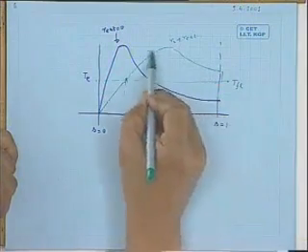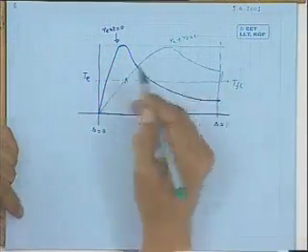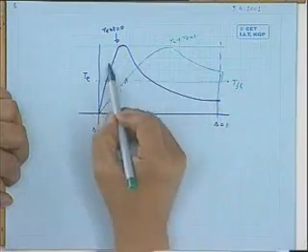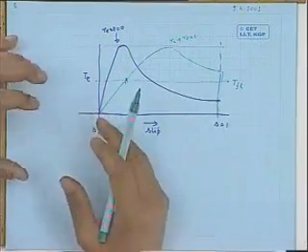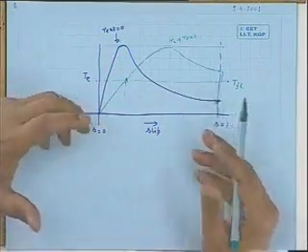So, as the machine now picks up speed, then like your DC motor, what do you do? You cut out that resistance. As the machine picks up speed, you cut out that resistance. This Tmax level is the same here. You go on, cut out that resistance gradually and bring it to 0. So, what have you exploited? You have exploited that the machine will operate with its own resistance ultimately.